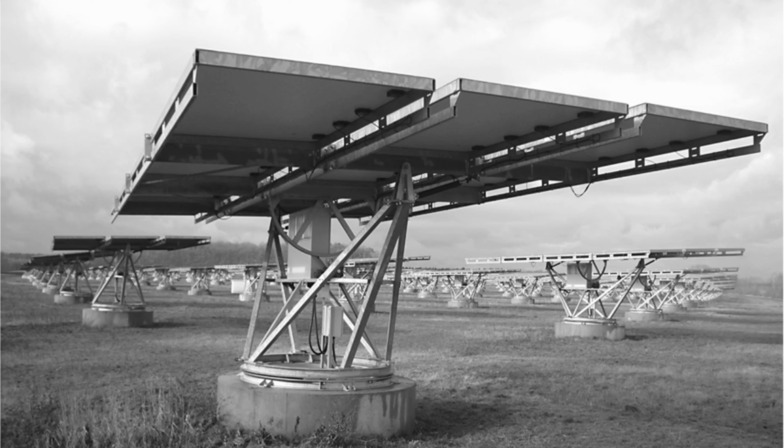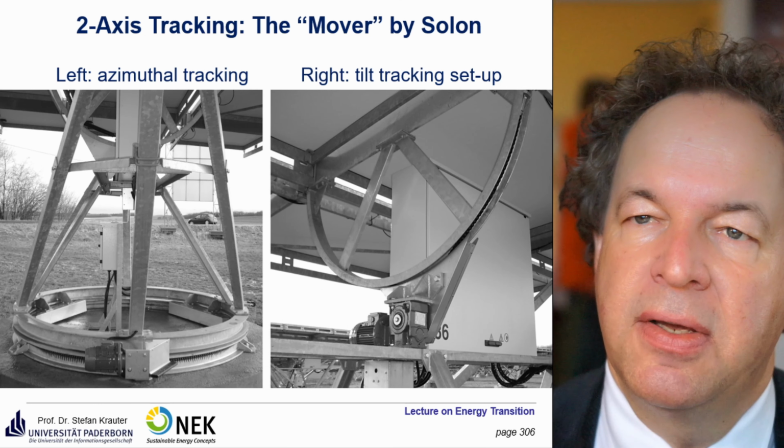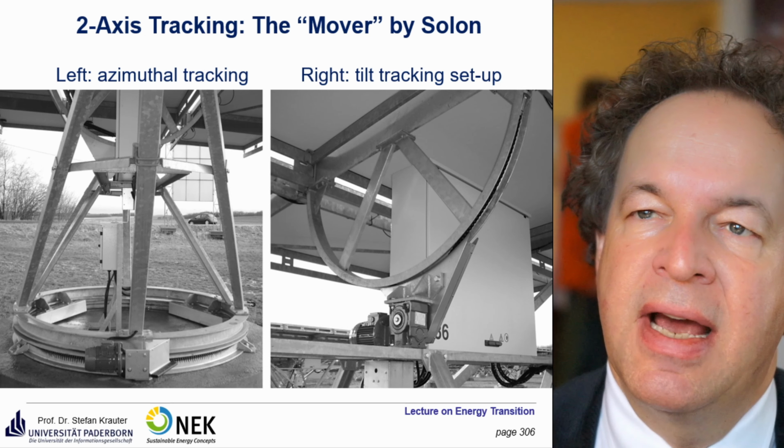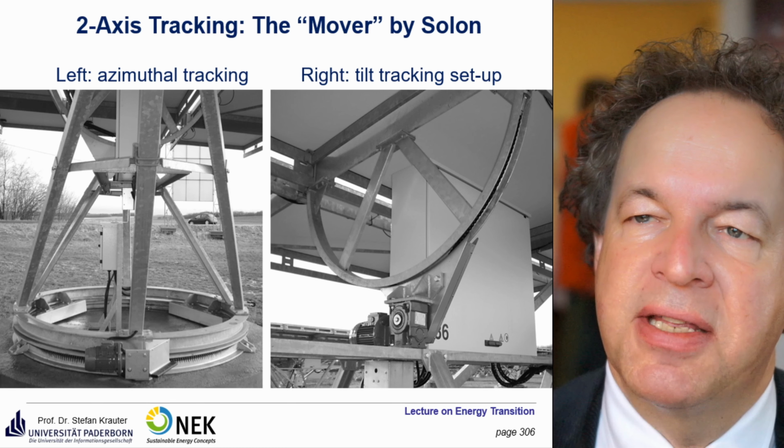Nowadays they're getting more interesting because the use of tracking system is more grid friendly, so you can generate more power also in the morning or in the evening. While if you would have a fixed system, it only generates maximum power usually during midday. You will see the azimuthal tracking and the tilt tracking on the right side.